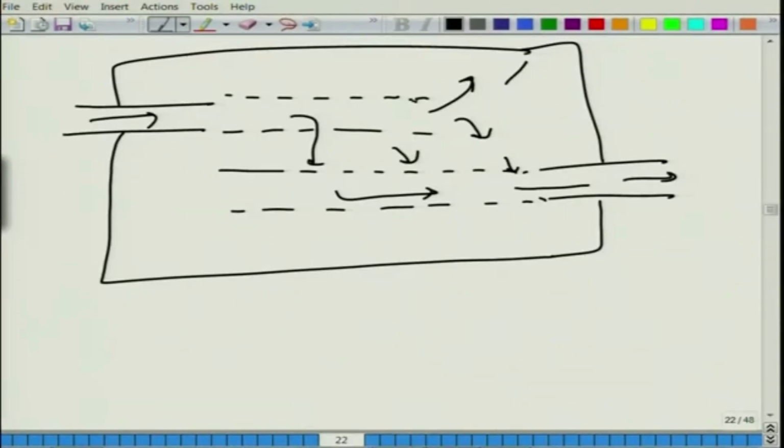Here the flow can of course expand and again do something like this, and you can also have things with an overlapping section. So, in such a case you can have this kind of a thing. These are called your open-ended perforated elements, because flow is just allowed to expand. So, here there is no guiding element. Okay. The little bit of drawback about this configuration is that it has a back pressure or head loss, because the flow is just allowed to expand, and who knows, it might be much more counterproductive compared to the case where the flow is easily guided. At least the flow cannot go through, there have to be resonances that are developed in this part. So, there are pros and cons for each muffler configuration depending upon your flow velocity and what you want to analyze. You can have different sorts of configurations.